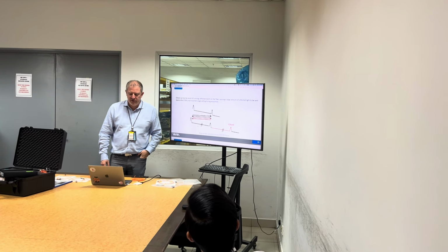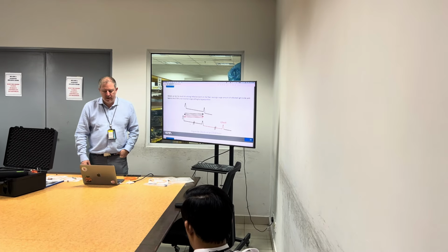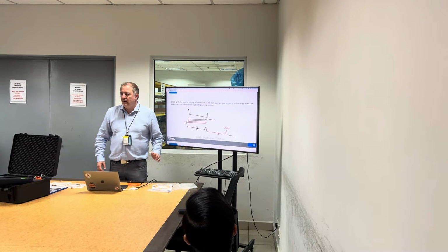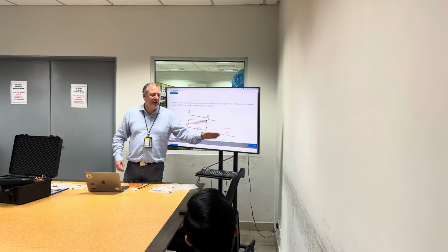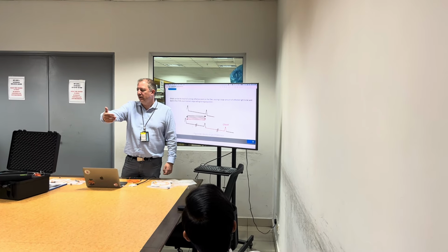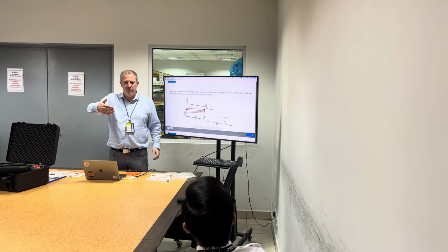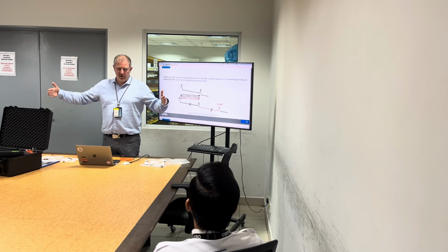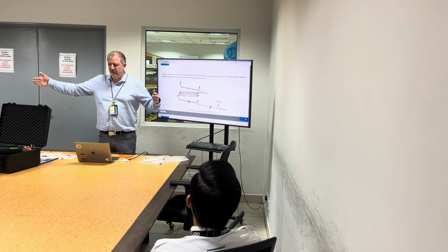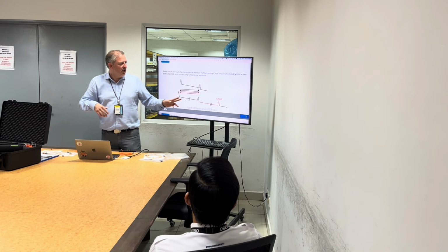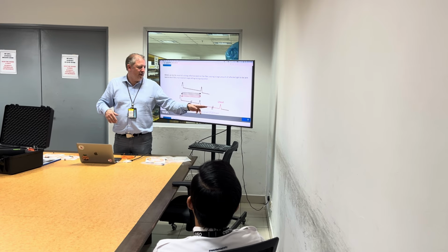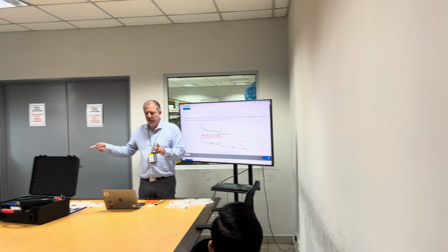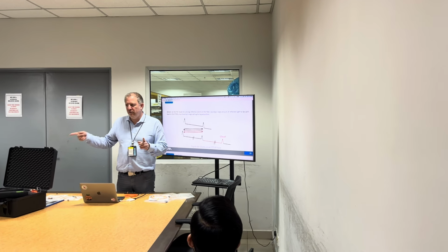Sometimes you have a ghost image, so don't be confused if you see additional peaks which appear to be after the optical fiber itself. You have, let's say, a 30-meter length in total, and maybe you see a fault after 30 meters. Usually it's because you have a big reflection and some light is going to go back and forth into the fiber optics if you have a reflection.